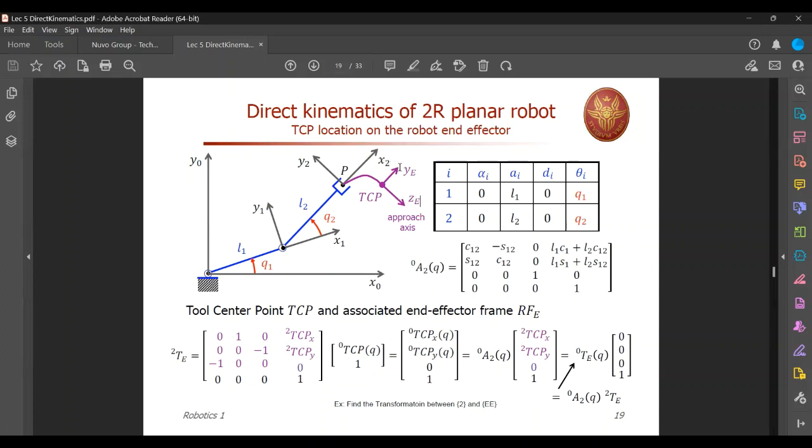When you are moving with respect to the end effector coordinate frame along y, it is actually with respect to along x direction in the second frame. When I am moving along z direction in the end effector frame, it is in fact negative y direction of y2. That is why you get this negative sign. Okay. See, -3.